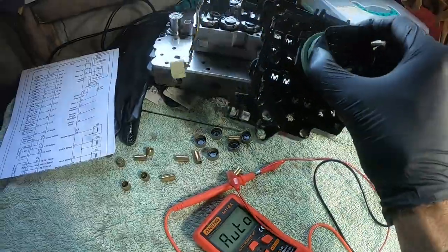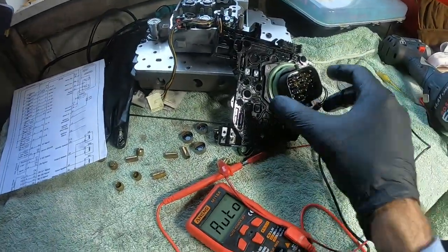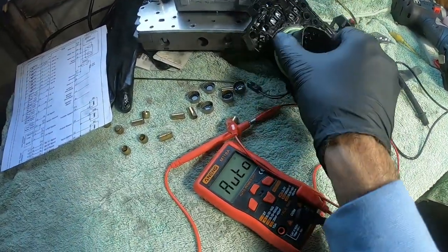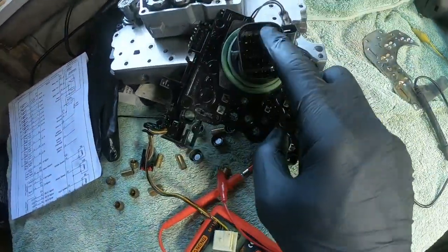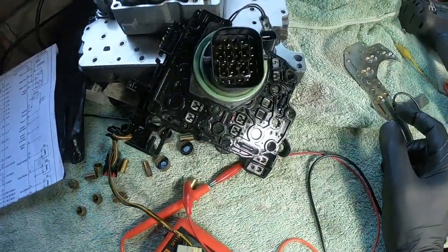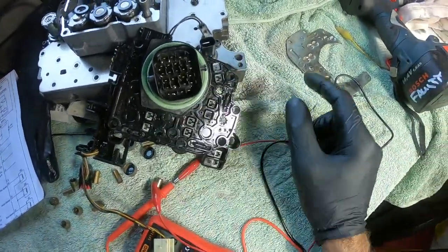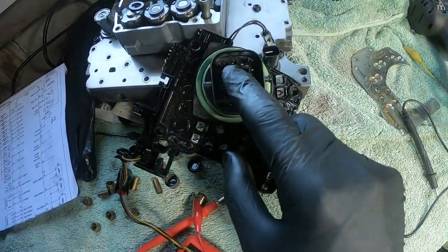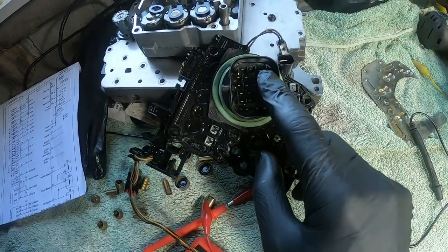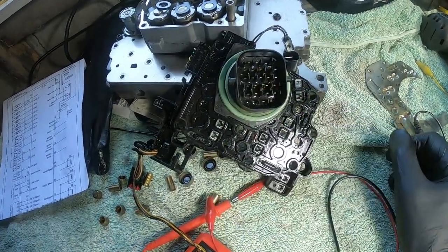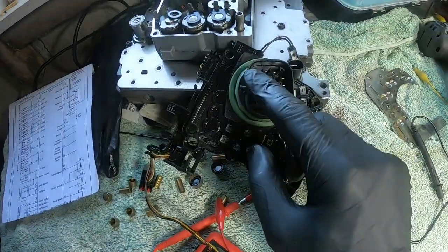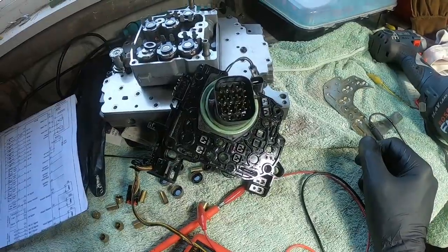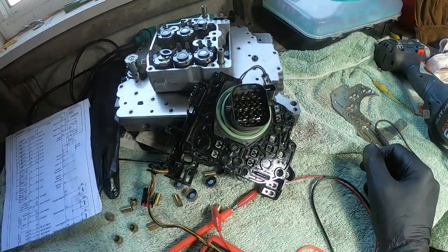one more thing is how to identify the pinouts for this. If you look at it, it has 3 pins over here and 3 pins over here. So where do you start the counting? Just keep in mind that you start the counting from the side which has one of the pins slightly at a lower position. For example, this one: the first 2 pins are at the same level, and the third pin is slightly lower than these first 2 pins. So this is 1, 2, 3. So I'll just go through and show you a couple of measurements on these pressure switches.